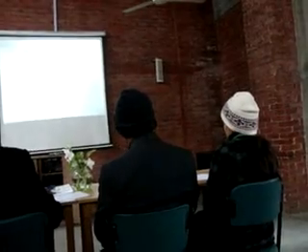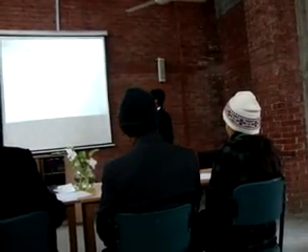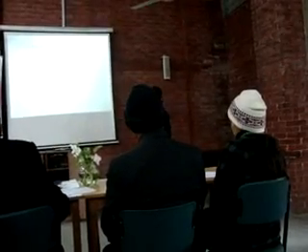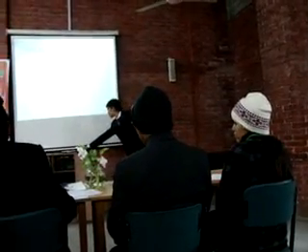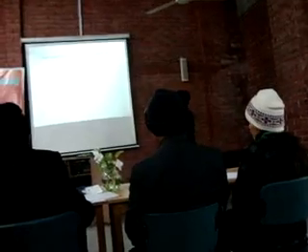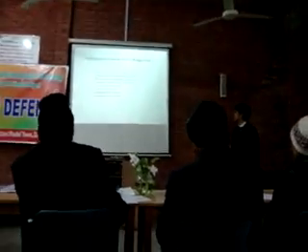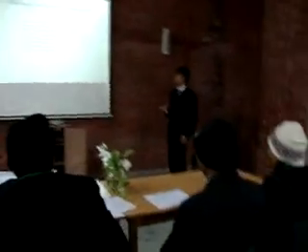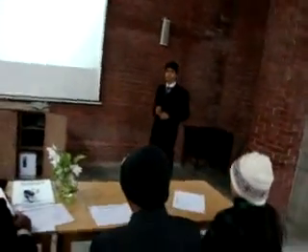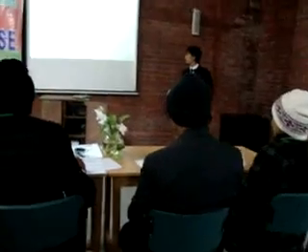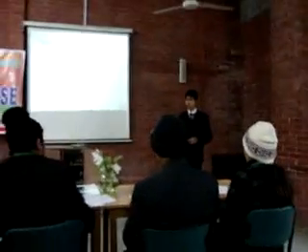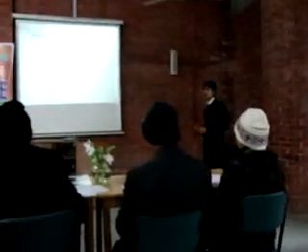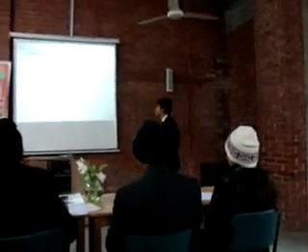PLC used in Niagara Textile. I saw two models in Niagara Textile, the TSX Micro 3722 and another model. Typical work done by PLC in Niagara Textile: speed control of induction motors, water level control, different types of temperature control, control of finishing machines, control of shift counter, identification of safety work, and emergency alarm system.